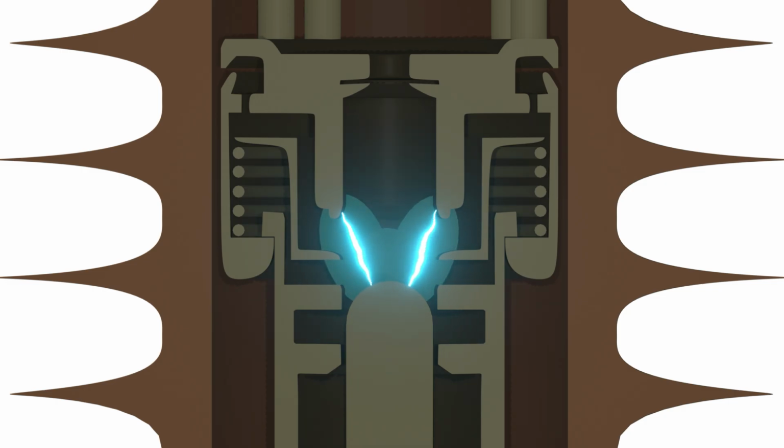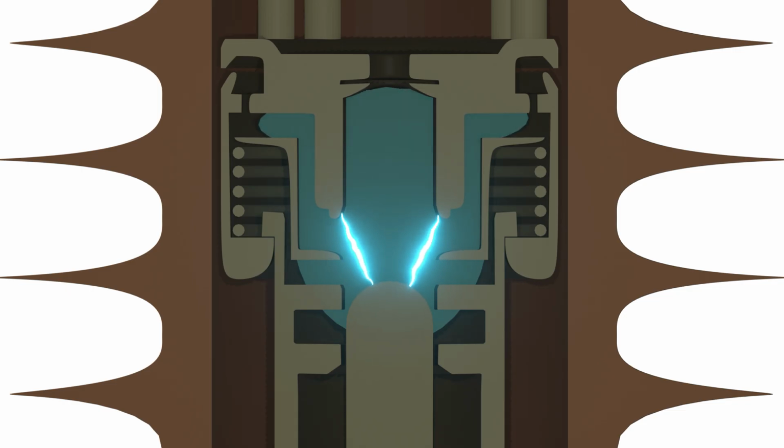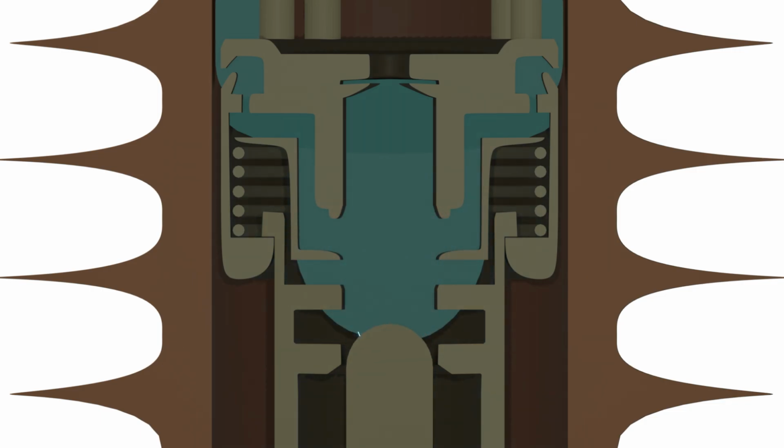The increasing hydrogen gas serves two purposes. First, it raises the internal gas pressure. Second, it forces the hydrogen to exhaust through the upper vent. This creates a flow of hydrogen gas. Hydrogen has a very high cooling effect and excellent deionization capability. Due to the combined cooling and deionizing action of the hydrogen flowing along the arc axis, the arc is quenched.